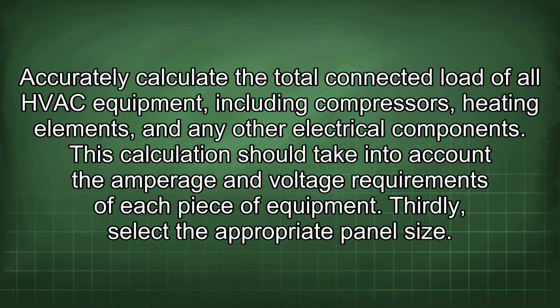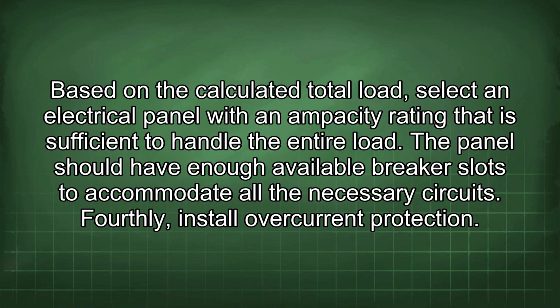Thirdly, select the appropriate panel size. Based on the calculated total load, select an electrical panel with an ampacity rating that is sufficient to handle the entire load. The panel should have enough available breaker slots to accommodate all the necessary circuits.